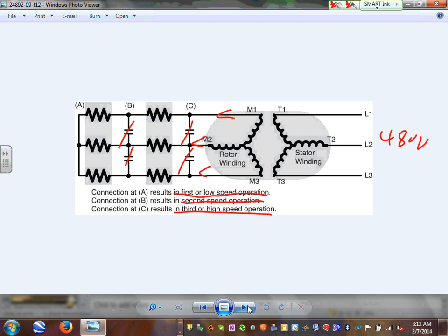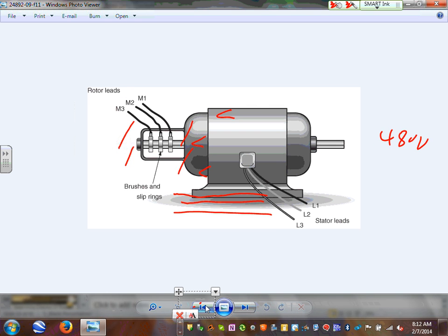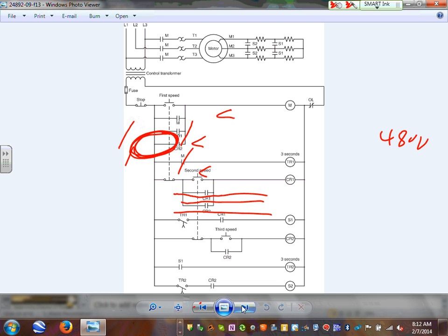Now, three of you guys have wired this in a lab, I hope so, Derek. When you put the slip rings there, three of you should have wired that one with us in our lab. So what is it? It's a specially designed motor where you can connect resistors to the rotor right in there. Why do we use it? It gives you more oomph as you punch holes in sheet metal. You need a lot of oomph. This is a good motor to get you more oomph than the induction motor, plus speed control.